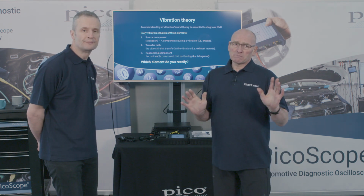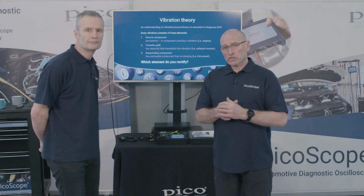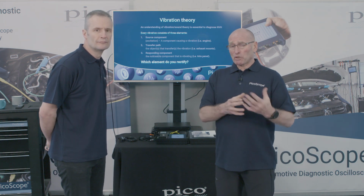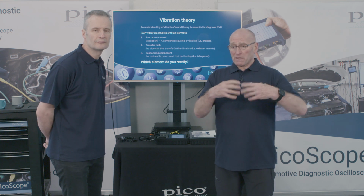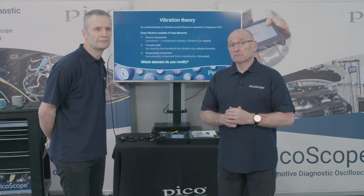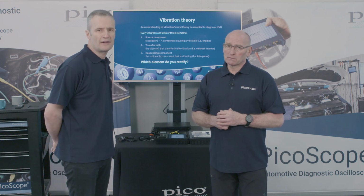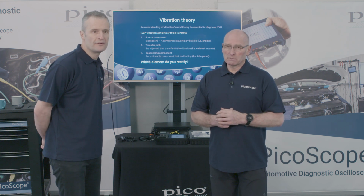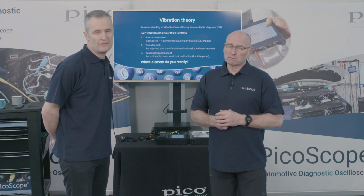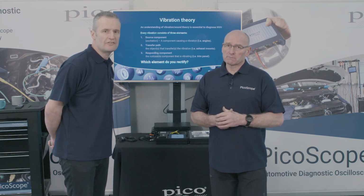I've got to admit guilty here, with all the experience I've had in the past dealing with noise and vibration. I think it would be fair to say that historically we've dealt with the responder. We've dealt with the bit that's creating the noise and not actually the source or the transfer path. Most certainly. Using a crude example, a misfiring engine is going to have excessive vibration. That will be felt in the cabin. Maybe the trims are now vibrating. Do we rectify the trim rattle there? Of course not. We go to the source. But that's a typical example.